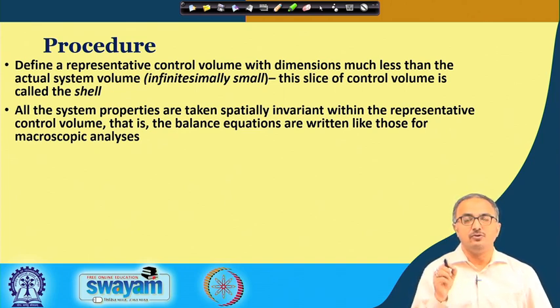So it is assumed that the scalar field has the same value over the entire control volume. Each control volume is taken to be a well mixed system, and when we take the limit of delta x, delta y, delta z to 0, we are reaching a point location. That is how we find out the profile of the scalar field.